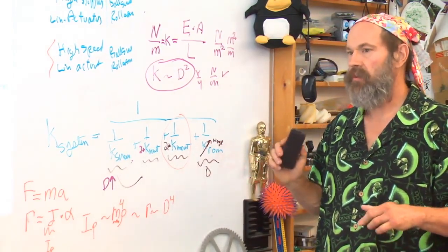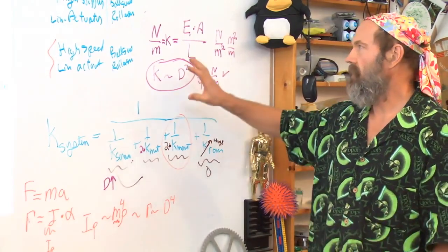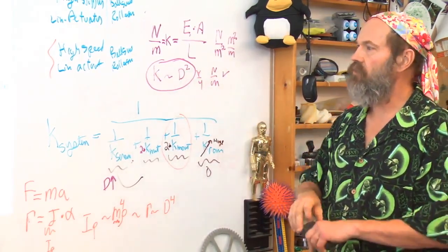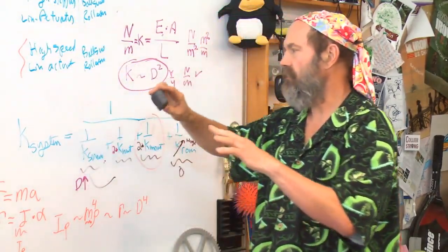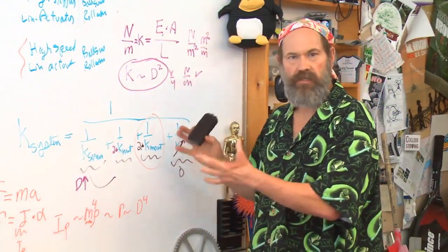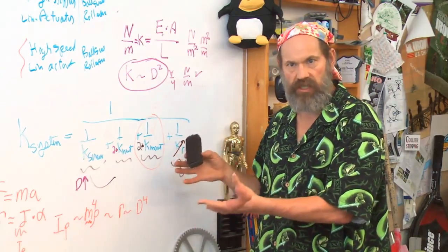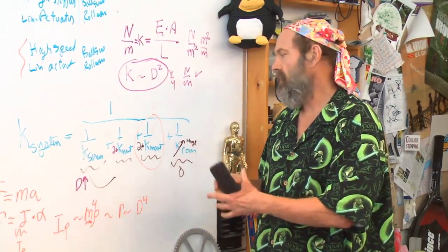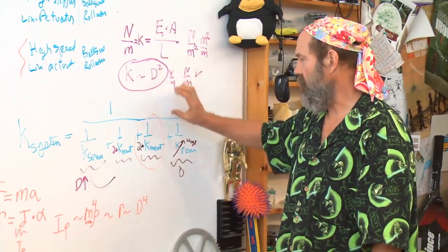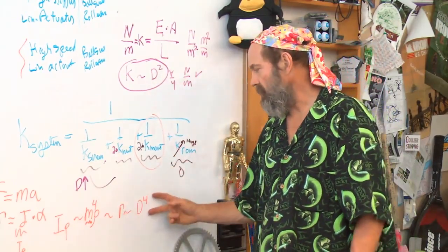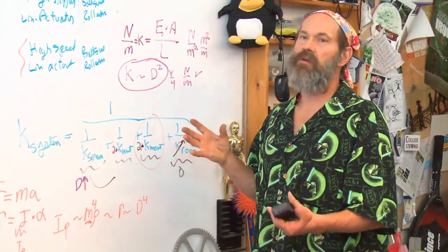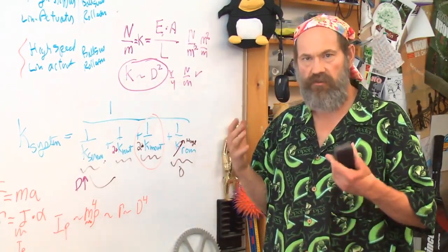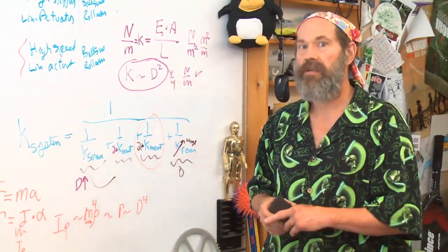But what's important is you understand in the early concept phase how you look at your machine, how you think about the structural loop, how you identify the dominant geometric parameters, particularly in your machine elements that are often highly stressed. Identify these relationships, and knowing these powers and the sensitivities to small changes in dimensions, for example, it gives you a powerful license to go after the low-hanging fruit.